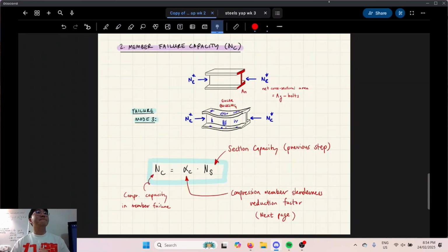So when it comes to section failure, how do we know if it's going to crush or fail at that local spot? It doesn't really matter, the formula covers both. Basically it's implying that if kf is 1, that failure mode is only going to be the yield failure, assuming it doesn't fail the member check.